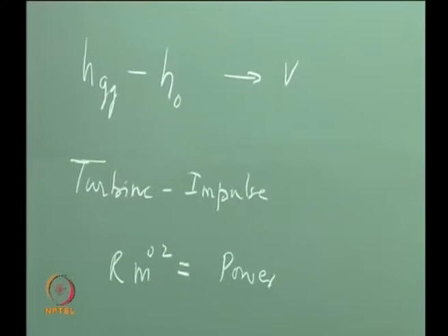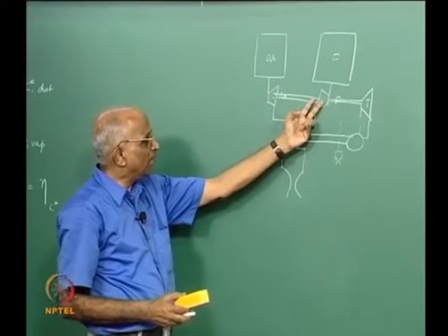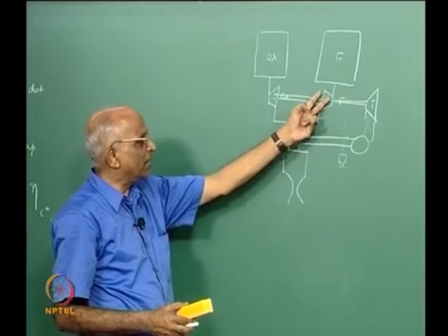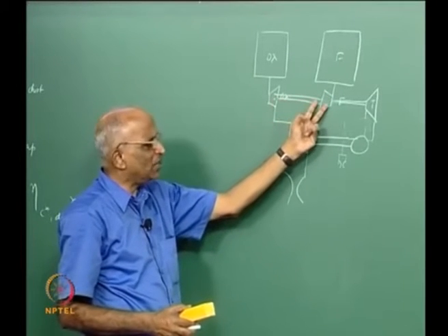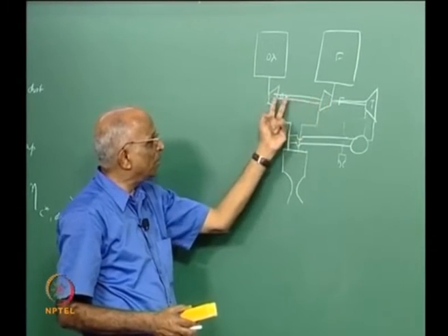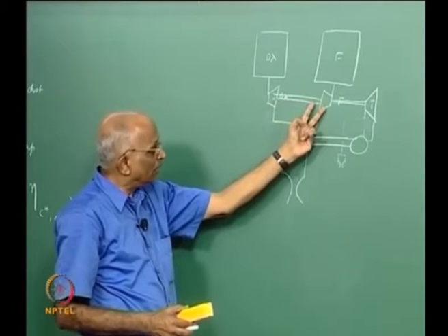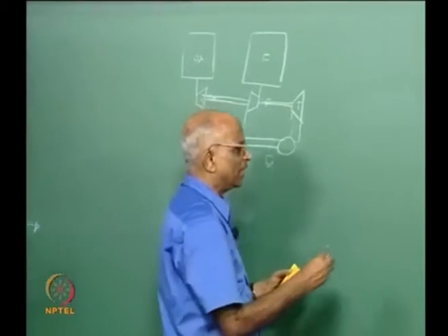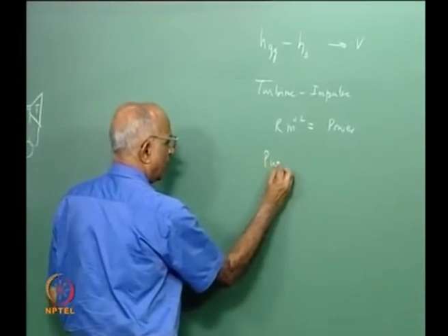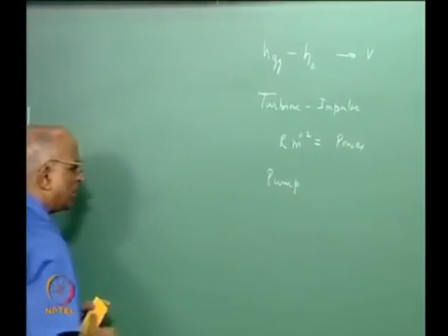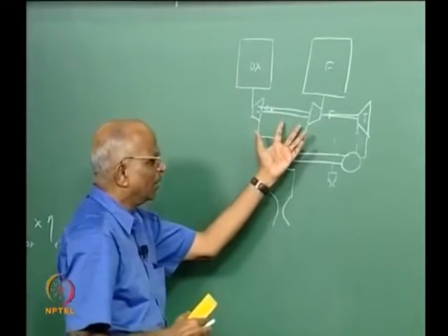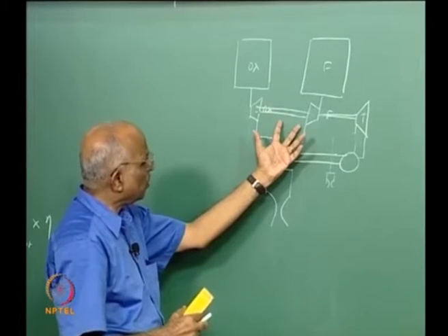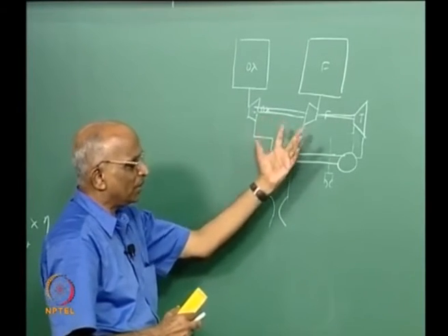Then I have the two pumps. Pumps, if they are for a small engine, could be centrifugal ones, wherein I have small flow but I need high pressure. It could be a series of axial flow pumps, or a combination of centrifugal, radial and axial and all that. Therefore, several possibilities exist for a pump. If you have to go into details of pumps, it becomes an exercise in turbomachines, and I will not go through it, but I also want to do some justice to pumps and turbines.